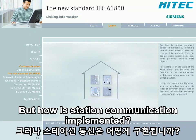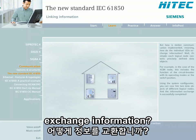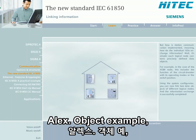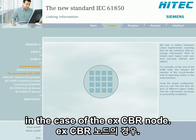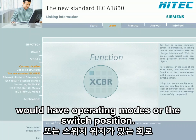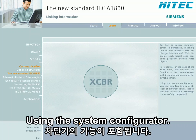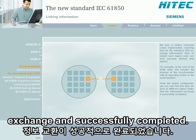But how is station communication implemented? Meaning, how do the individual IEDs exchange information? Well, it's simple. Each logical node contains precisely defined data objects. For example, in the case of the XCBR node, this includes the function of the circuit breaker with its operating modes or the switch position. Using the system configurator, you can now link two data objects of different logical nodes, and your information exchange is successfully completed.